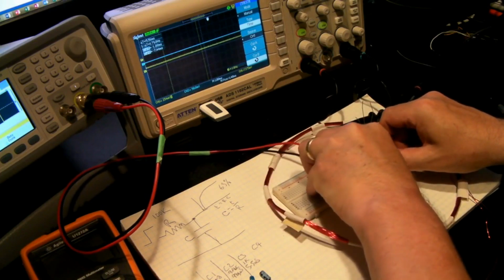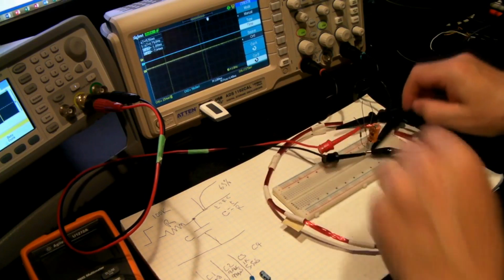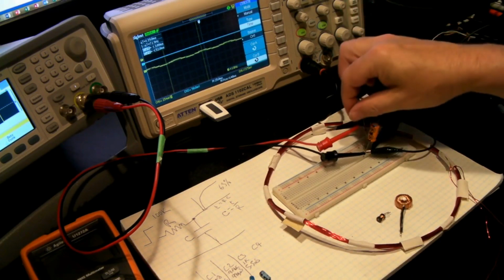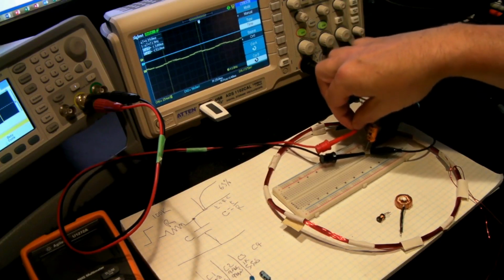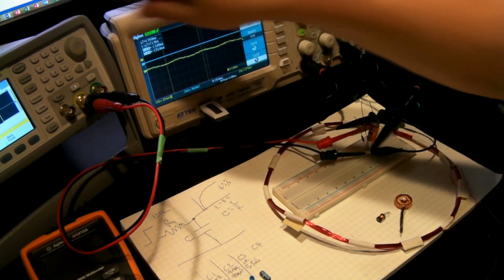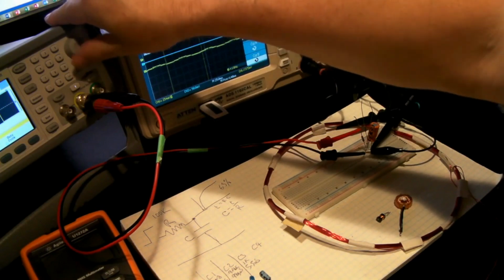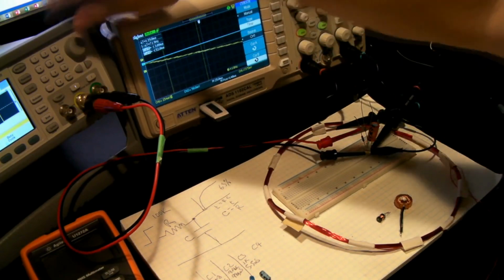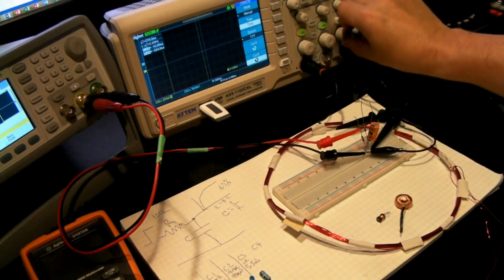and the signal negative. Alright, so this one's going to be a lot slower, so I'm going to reduce the time base down. And as you can see, it's not getting enough time, so we're at 10 hertz, so I'm going to reduce it right down to probably about 1 hertz, to give it a chance to charge.